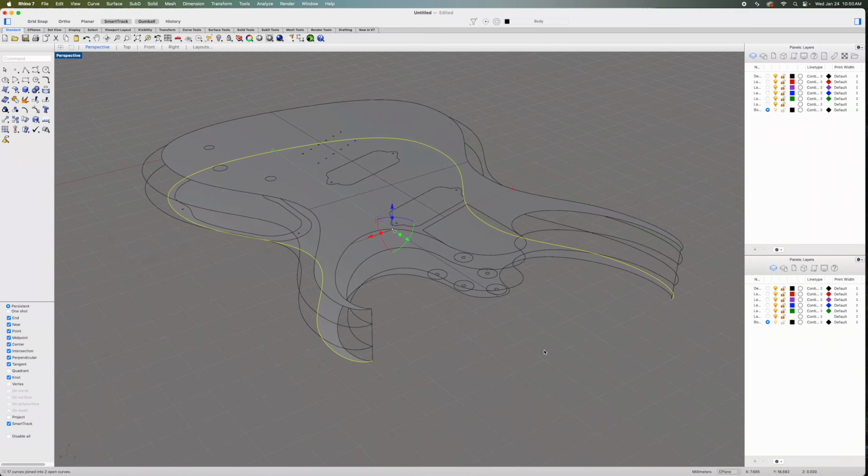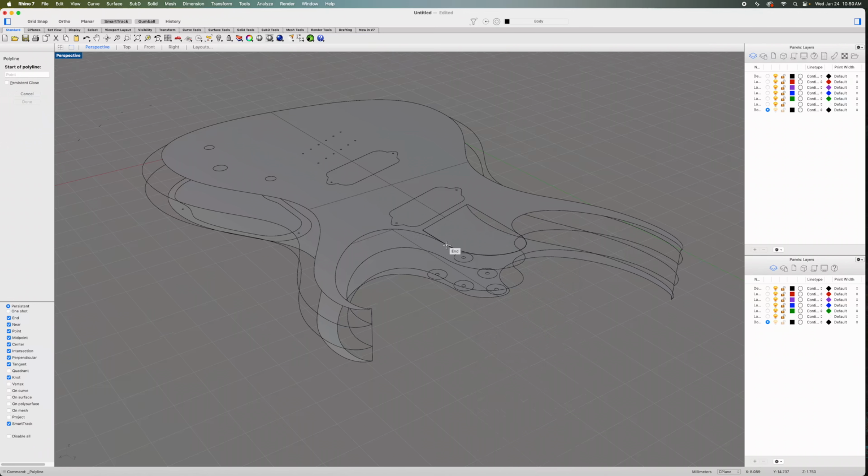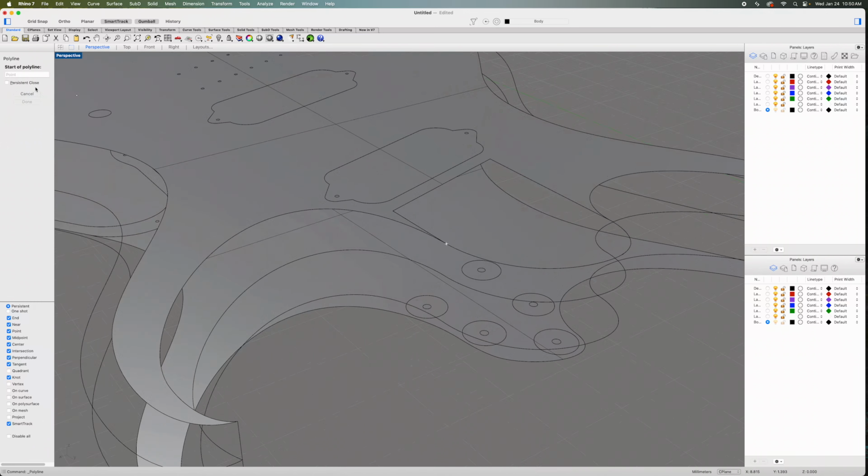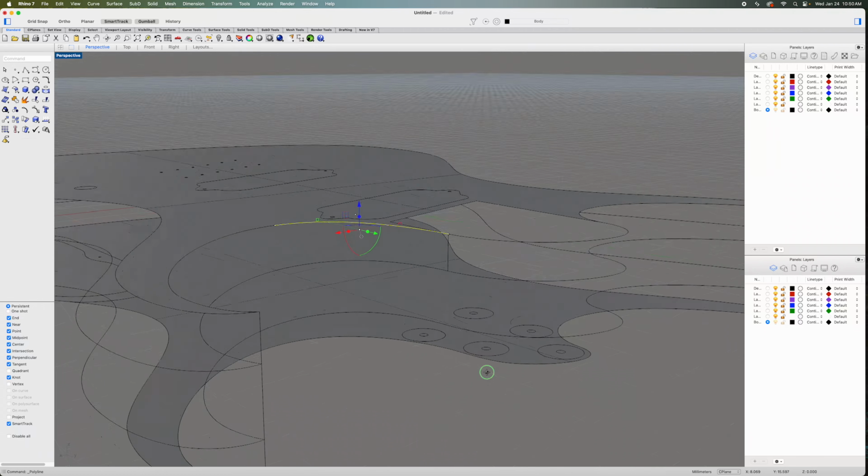Now I have to draw some structure lines. So I'm going to select the polyline tool, because I need to join this end here with this end here. I'm going to select this line so I can see where the line is. I'm going to grab my poly tool, click over here on endpoint intersection, bring this down to the end intersection knot, left click, right click. And now I've drawn a line.